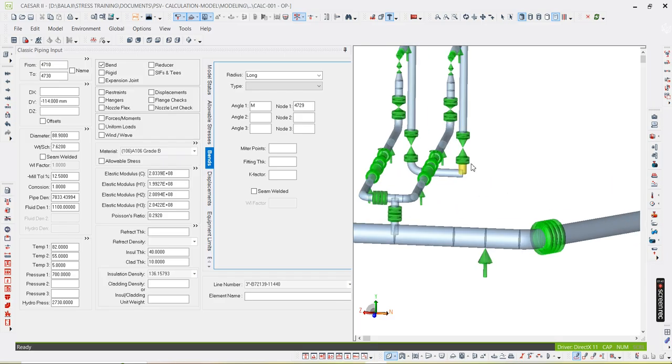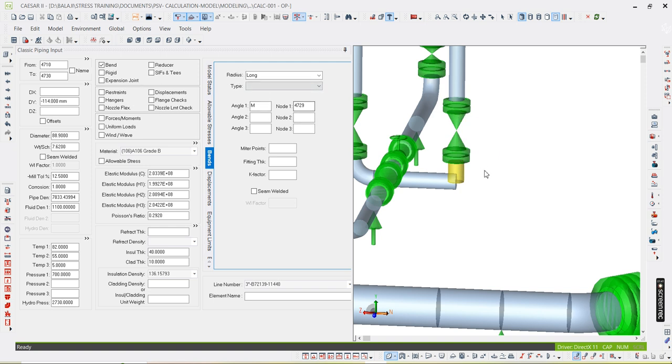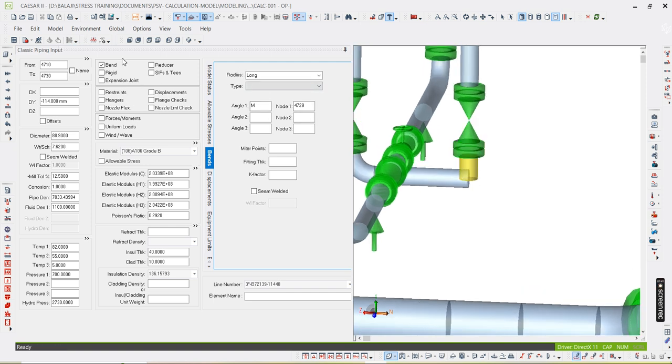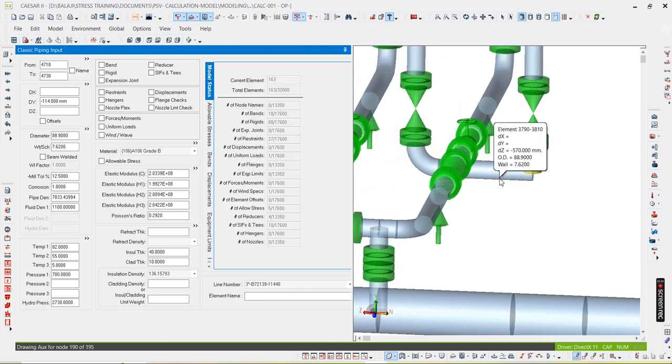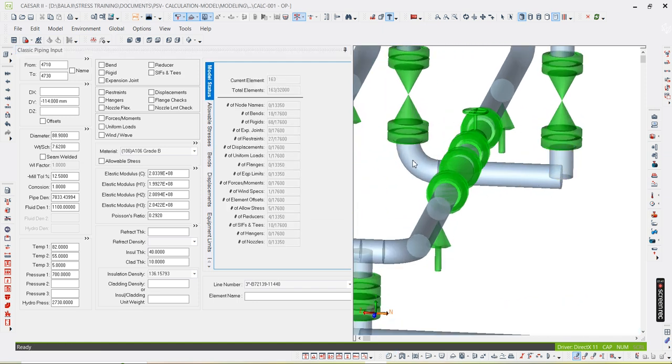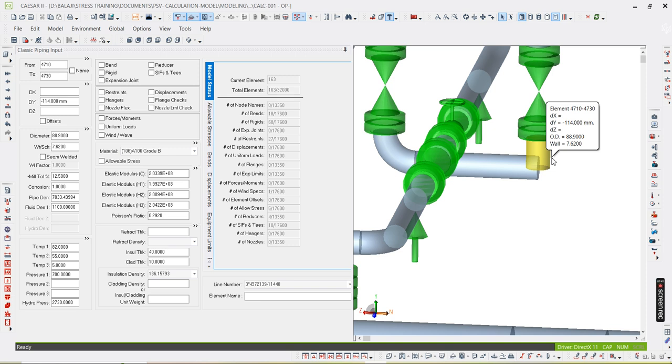Okay. So here what we need to define, here a bend is there. You delete this bend, because the reason the bend has appeared is that we have copied this node number, no? So here a bend is there. So you need to do it properly. So once you complete the copy option, you need to check properly.